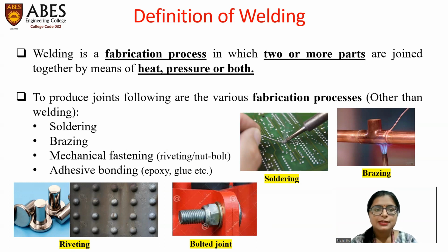Okay. So the basic difference between soldering and welding is the melting. In welding, both the base metals are heated, and the filler wire is heated and melted and fused together, whereas in soldering, only this wire or solder is heated and melted. There is no such melting at the substrate.